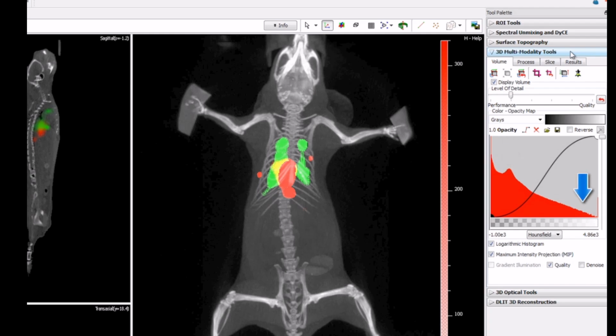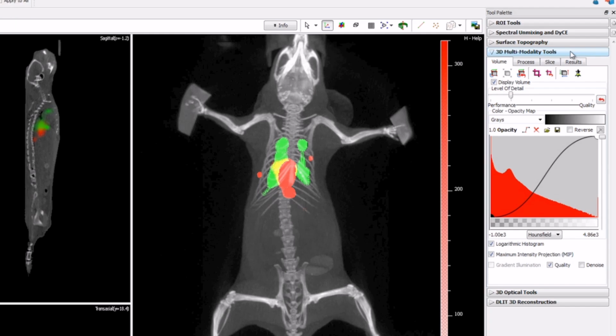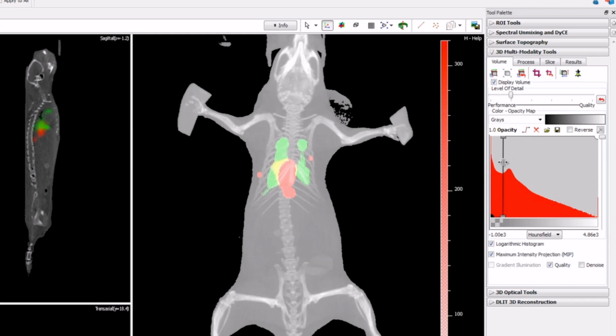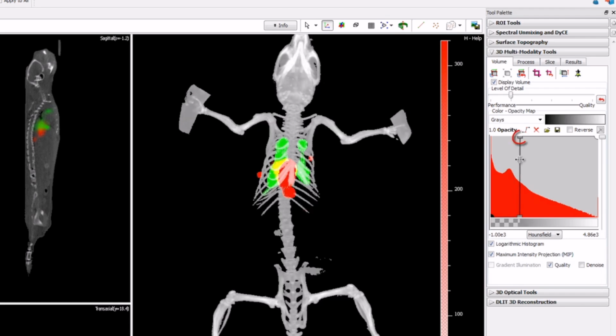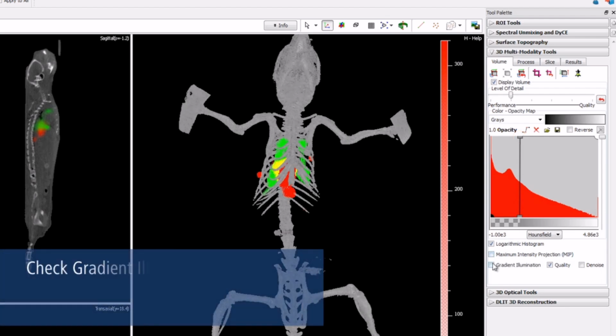The default view is a blended view showing some low-density voxels and some high-density voxels. In this study, we only wish to show the skeleton, so let's start by clicking the AutoFit Air Noise Boundary button. This effectively takes a slice from the histogram that shows the skeleton of the animal bounded with the surface of the animal. Now grab the boundary bar and slowly slide it to the right until only the skeleton is visible. You can double-click on the top of the bar to adjust the color of the voxels above the threshold. You can also crop the image and adjust the opacity with the provided slider.